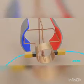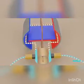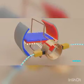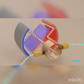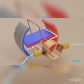So first, the brushes are in contact with these 2 commutator segments, which turns on this electromagnet, which causes it to start spinning. Once we get to here, the brushes switch contact to the next pair of commutator segments, which means this loop turns off and the next loop turns on. Now this electromagnet wants to spin. The brushes switch contact and the next loop turns on. This keeps happening as our motor spins. It's almost like the loops will take turns being an electromagnet.